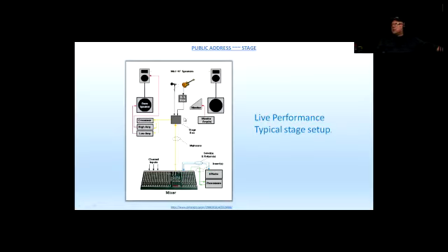And if you have something that's 4 ohms, the speaker is looking for 4 ohms, and the wire itself could sometimes have 1 or 2 ohms of internal resistance, then the impedances are too close, and we're not going to have a system that's efficient enough. So usually we try to put the main amplifiers on the stage, which are supposed to service the loudspeakers that are on the stage. Okay, so we want to have those closest.